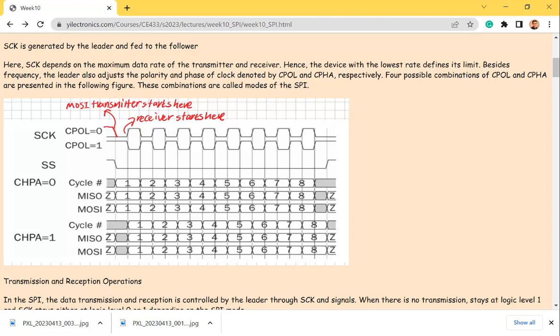But how many pins do you have for the SPI? Just the SDO and SCK, just 2. So it's a serial communication. The SDO is a data output, serial data output, sending out bit by bit and being clocked. Make sense? Yeah.